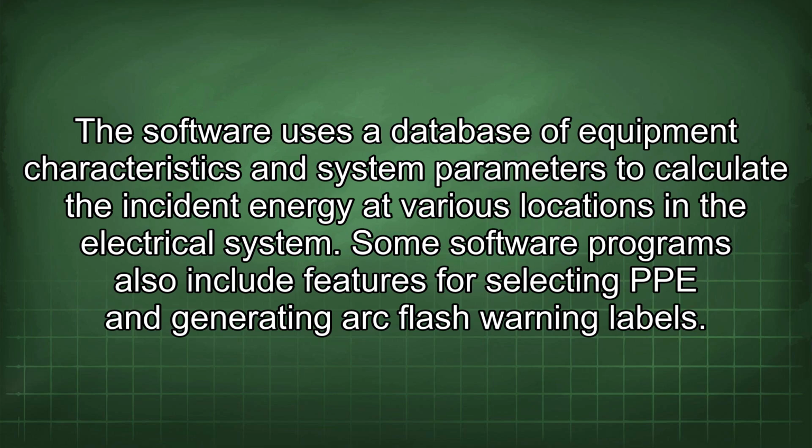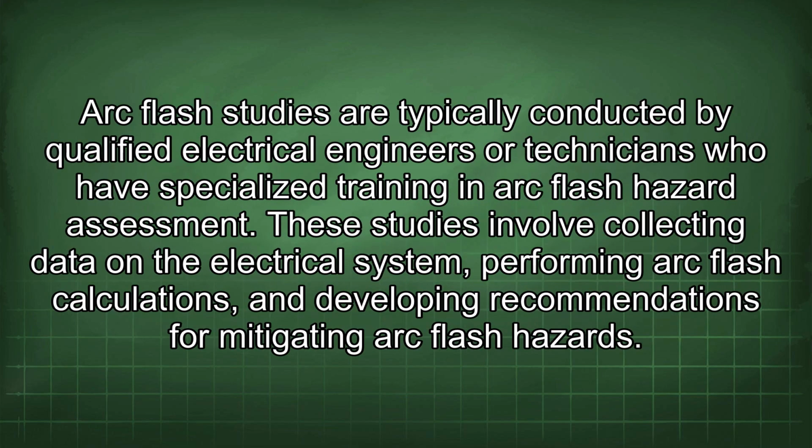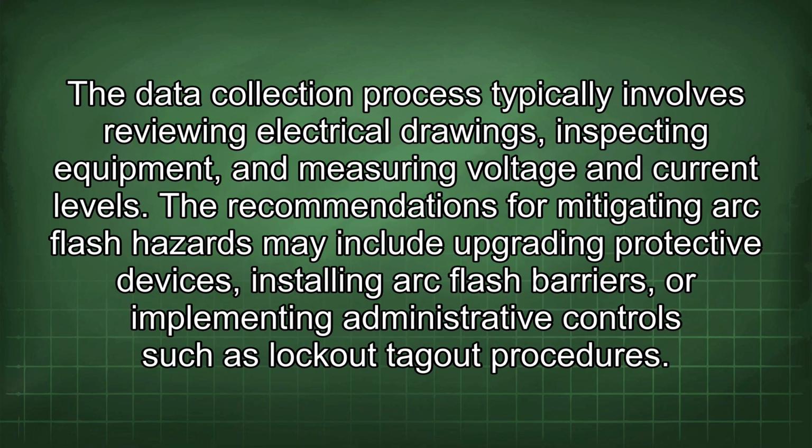Some software programs also include features for selecting PPE and generating arc flash warning labels. Arc flash studies are typically conducted by qualified electrical engineers or technicians who have specialized training in arc flash hazard assessment. These studies involve collecting data on the electrical system, performing arc flash calculations, and developing recommendations for mitigating arc flash hazards. The data collection process typically involves reviewing electrical drawings, inspecting equipment, and measuring voltage and current levels.